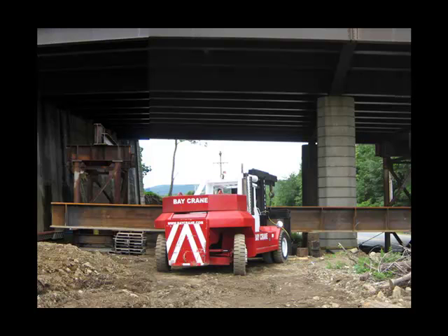The innovation here was to shorten the span, and that meant you could construct the new supporting abutments inboard of the existing abutment. On the extreme left, you can see the existing abutment, and the new abutment to be built inboard of it pretty much occupies the space shown here, occupied by the bay crane. In order to free up that space for construction of the new abutment, this existing column was in the way and needed to be removed.